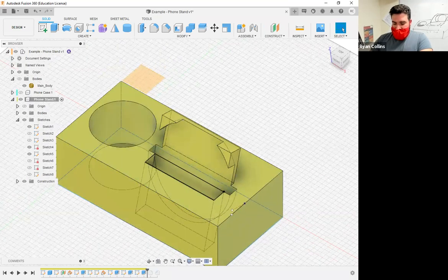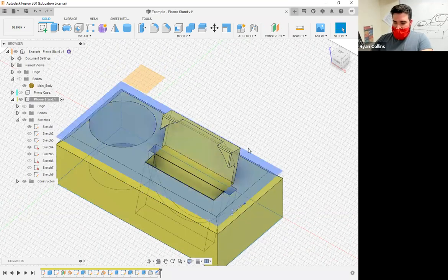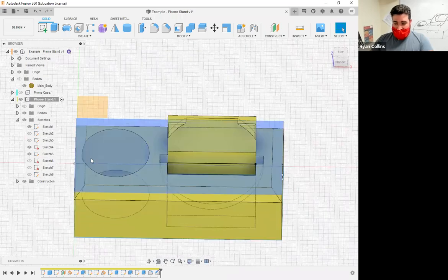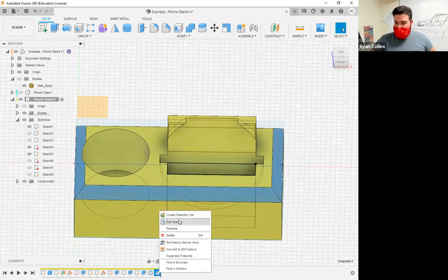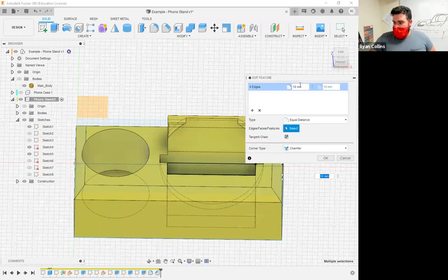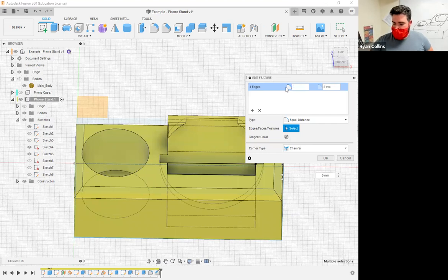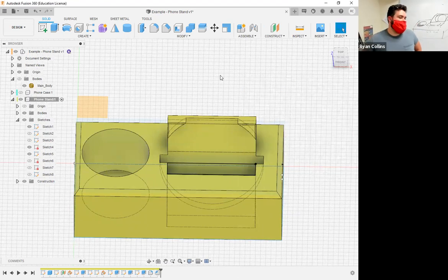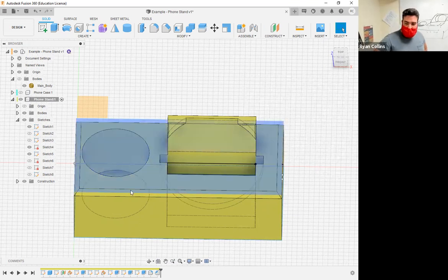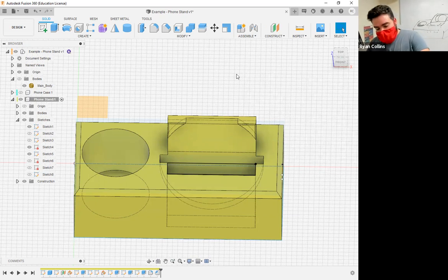Now, when I use the fast forward, go back and reapply stuff, and this is the problem, like, all right, my chamfer was way too big. I need to now go back, adjust that chamfer. And we'll make that more like 8. Smaller. 5. Yay. So it's easy to work with stuff like that by going back and forth through the history slider. All right. Let's save this.